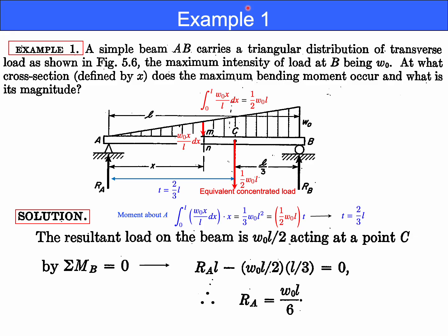So we can replace the distributed load with this equivalent concentrated load. In order to find its application point, the next question is, where is this force applied? It is not the center. That is different from the previous uniform distributed loading. The centroid is a little bit to the right of the center.